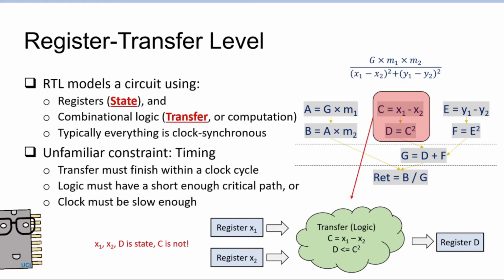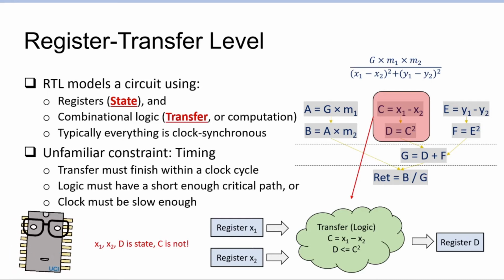The tools try their best, but the programmers themselves have to be aware of the impact that the code they write has on the critical path of each of the RTL levels. And if your circuit results in a slower clock speed, then that across the board results in slower performance, slower throughput, slower everything. So that is a very critical part of your accelerator design, which complicates things.